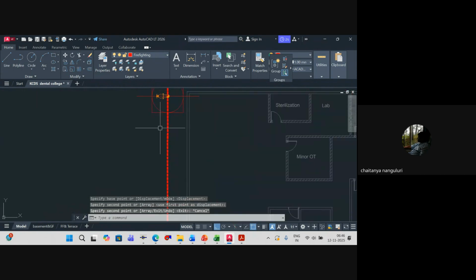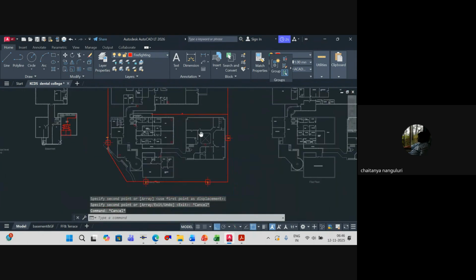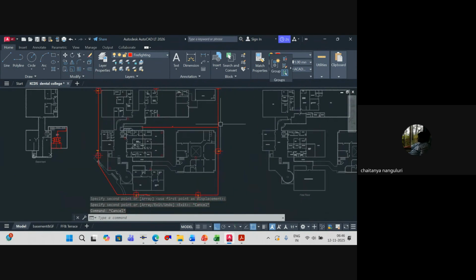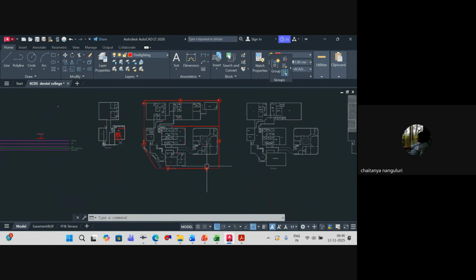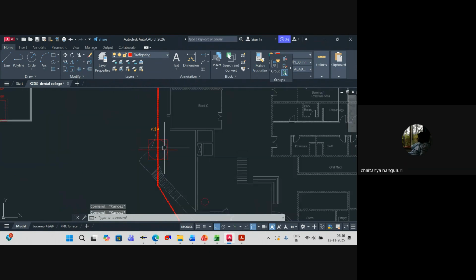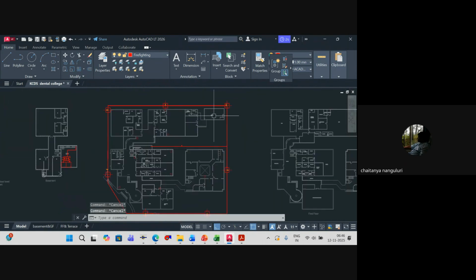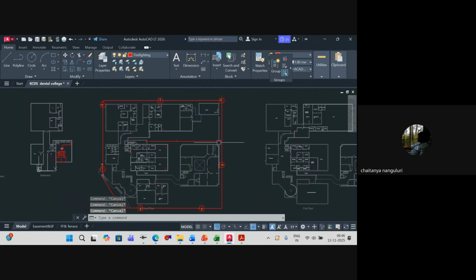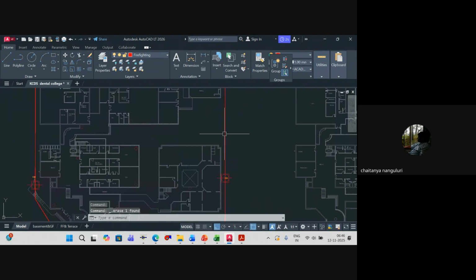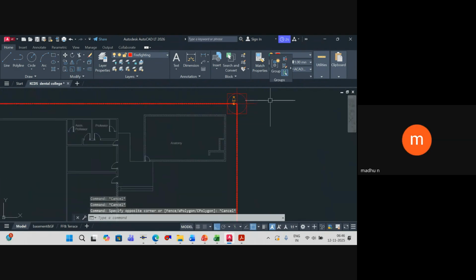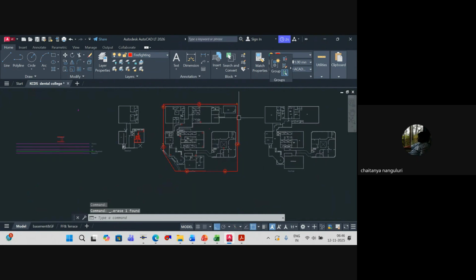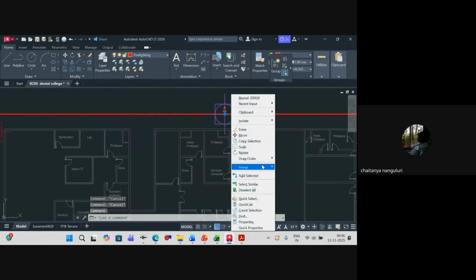We have it at this location. I guess this distance is long. So how many do we have? 1, 2, 3, 4, 5, 6, 7, which is sufficient for us. So we have placed them at a distance of approximately 60 meters. You agree? Yes. So this becomes our yard hydrant circuit. Simple.